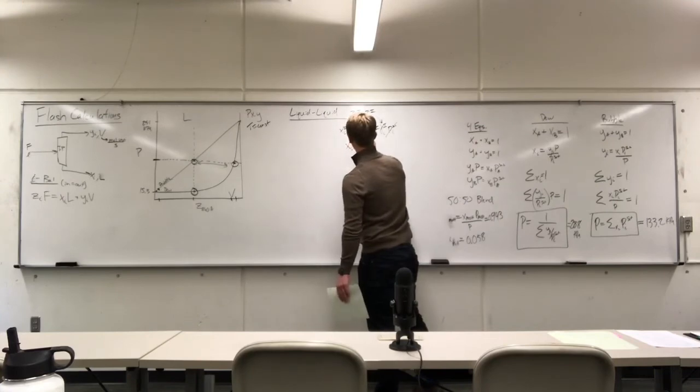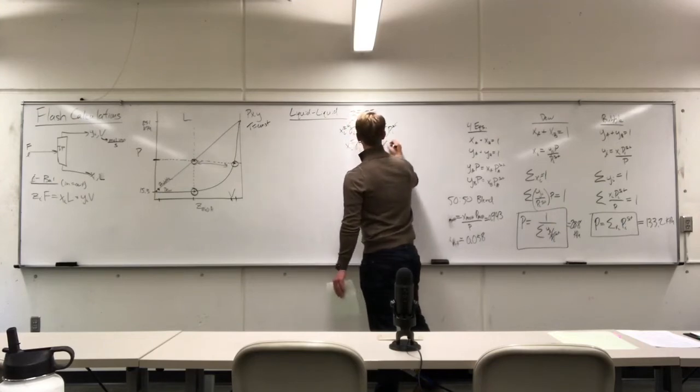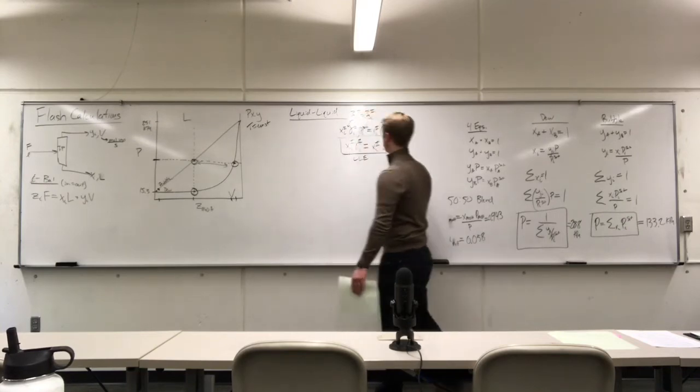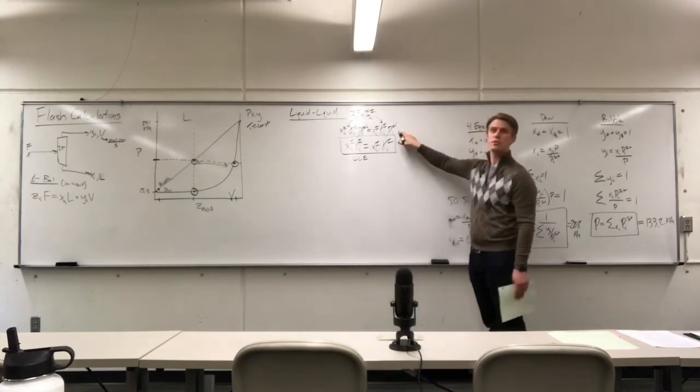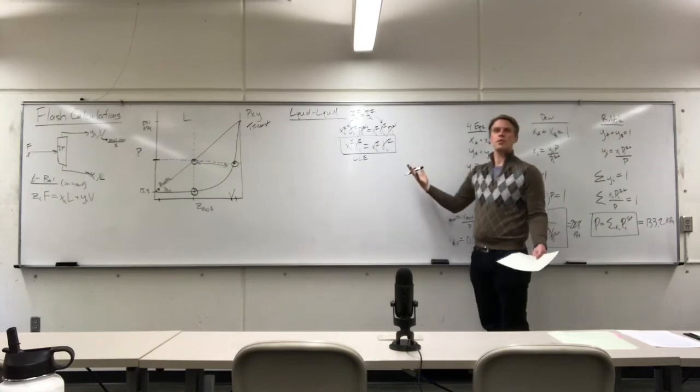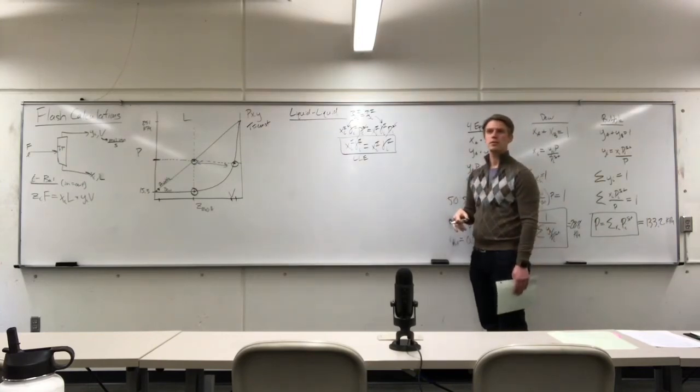And the equation that we have to solve for every species in the system for liquid-liquid equilibrium simplifies down to this here. In fact, we didn't even have to assume that this is a low-pressure system, right? Because the pure fluid fugacities would have canceled out regardless of how ideal or non-ideal it is.